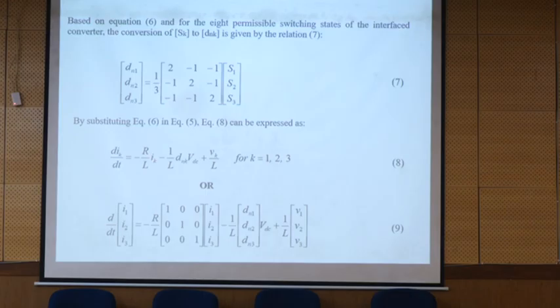And we have ICA, the injected current from the converter to the grid, and also VCA, which is the voltage of the point of common coupling, the point where the converter is connected to the grid. So if the voltage changes, we see that the current changes also.